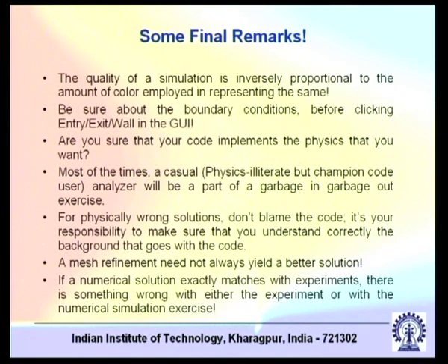This is very tempting, because what we commonly see is that you click, for example, the outflow boundary condition where it is not exactly outflow. Let us give an example. Let us say you have a thermally fully developed flow along x. Then it is not ∂T/∂x equal to 0 at the outlet, but ∂θ/∂x equal to 0, where θ is (T minus T_wall) by (T_bulk mean minus T_wall). If you are solving for temperature, you will most commonly be tempted to click the outflow boundary condition because it is available with the GUI, but that will be totally wrong if you are implementing a thermally fully developed flow. You have to somehow implement ∂θ/∂x equal to 0.